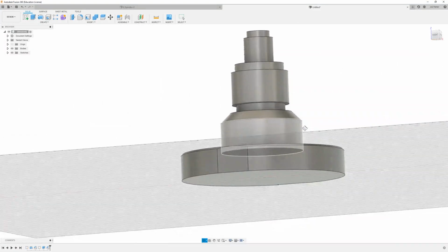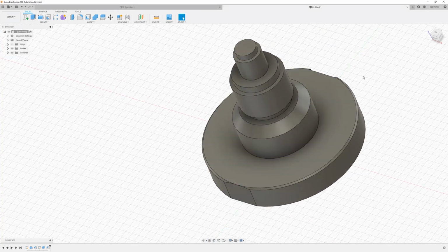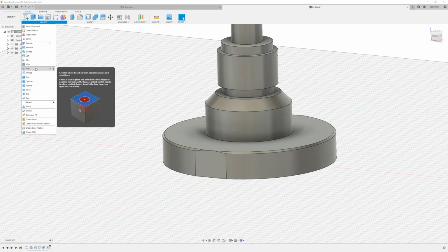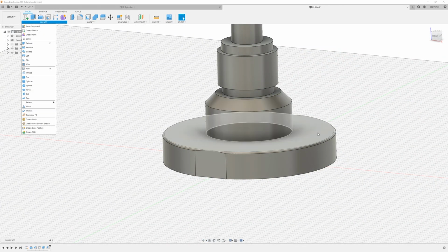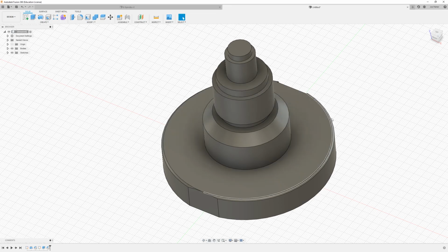Okay, I'm nearly done now, so I need to place the hole feature in one side of my component. What I would normally do here is go to Create and Hole, and then place that on the face where I need to create the hole. Now, one issue that we might encounter here is being able to set the hole in a particular place on that face which is not concentric with this cylinder, or the base cylinder.